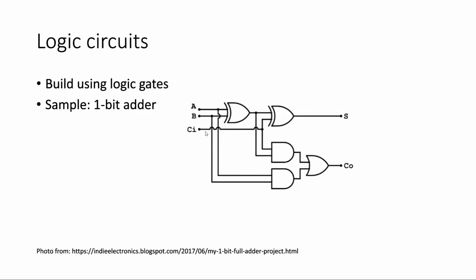In the beginning of an addition, the carry is always 0, but in the next bits, as we saw earlier in the first part of the lecture, it can be 1. And you see how many gates are put together to just implement this simple operation. We have 2 XOR gates, 2 AND gates, and an OR gate. And this is the result of the sum, and this is the carry of the sum. So this will be used in the next bit if you want to add up more bits together.